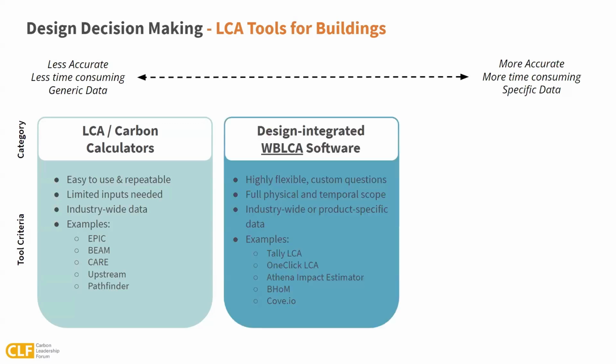Next is design integrated whole building LCA tools. These are usually more robust and customizable than calculators and allow for the assessment of full physical and temporal scope using actual material quantities. Examples of these include Tally LCA, One-Click LCA, and Athena, and these are the tools we generally refer to as whole building LCA tools because they enable modeling a more comprehensive physical and temporal scope.